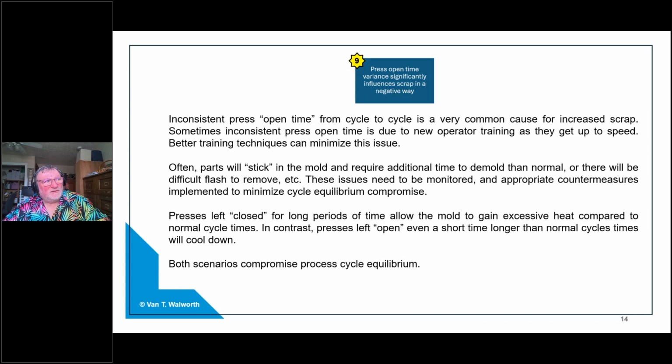And so if a press is left too long in one way or the other, either left open or left closed, we might have parts that are sticking in the mold and causing variances in the time that the press is open and being serviced, which then changes the dynamic of the pressure gradient or the thermal gradient, causing the parts to have a different state of cure when they're being cured.